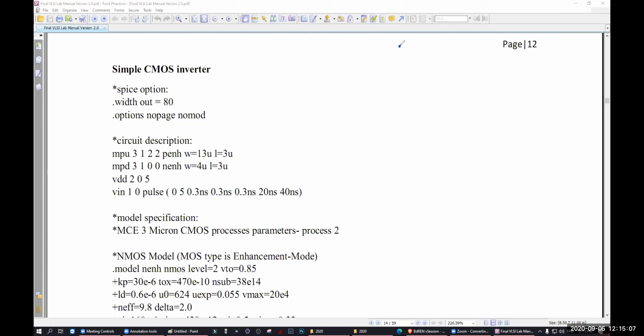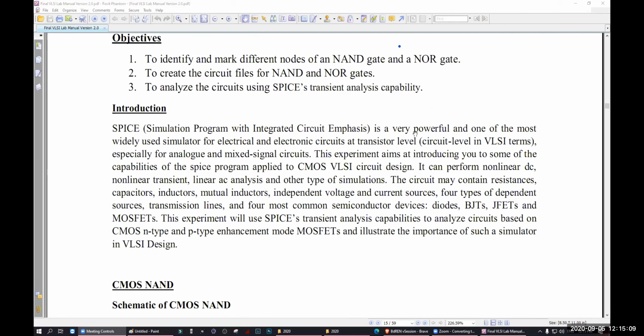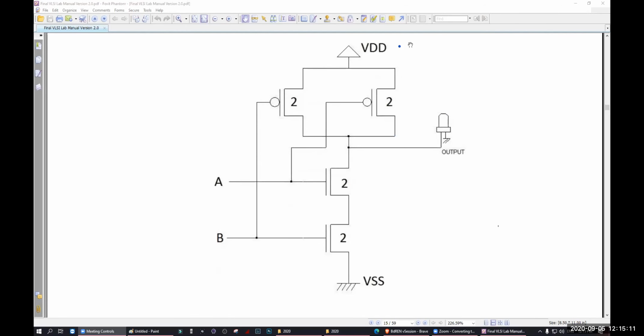Let's go back. Now this is our CMOS NAND gate. Here we have to do the sizing first. Although we have written 2, 2, 2, 2, this will not be 2 and 2. This will be 2 for this lab, because we are considering 3:1, right? WP by WN is 3:1, right? Yes, sir. Okay. What do I mean by these? I mean these.